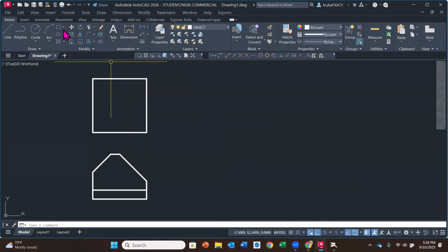So going back over here, we are going to do that offset command. A distance, actually 0.5 was my last one, so I can just hit enter. I'm going to select that bottom line and go up. And then I'm going to select the top line and go down because they're both the same distance. Okay. All right. So those are the 2 feet.